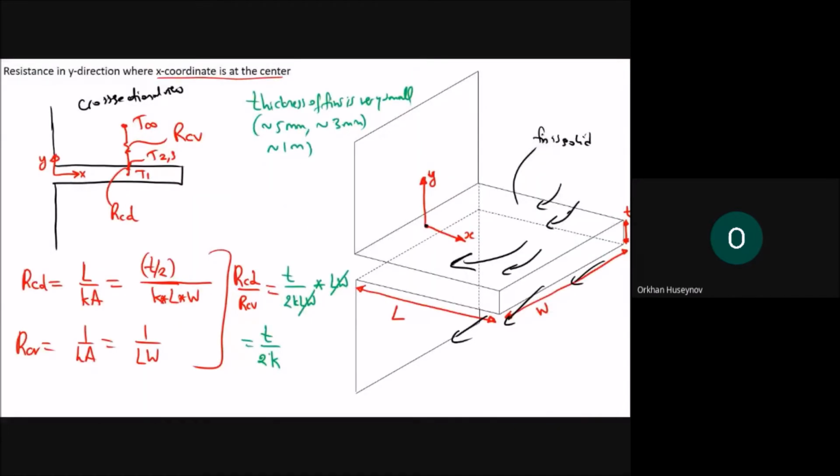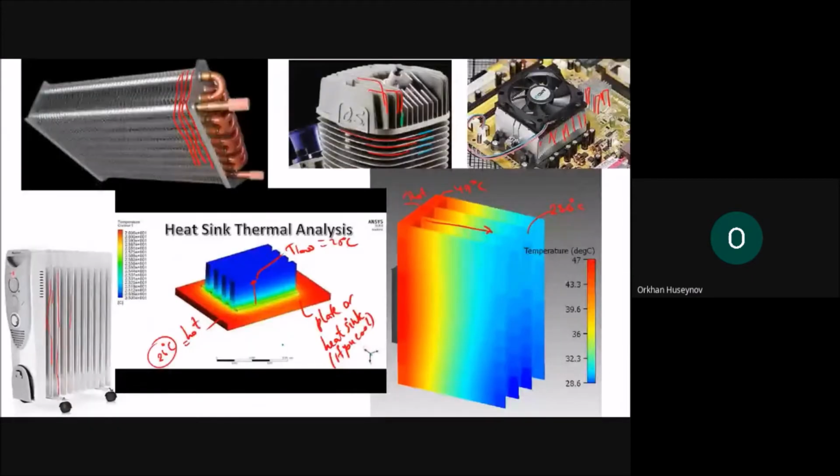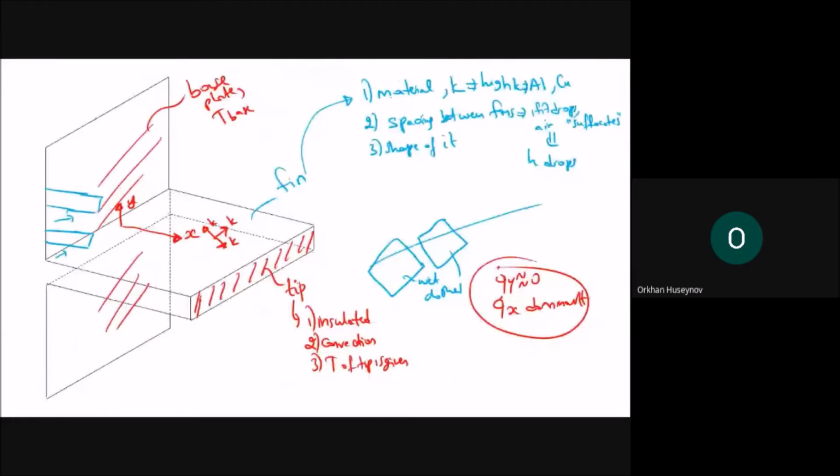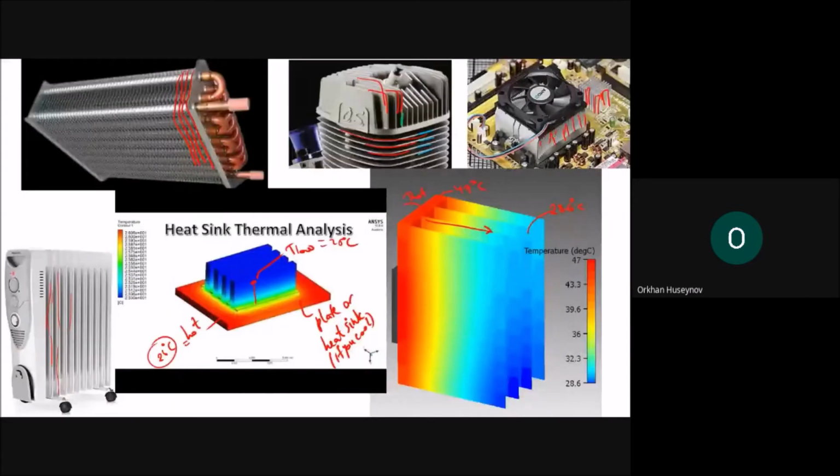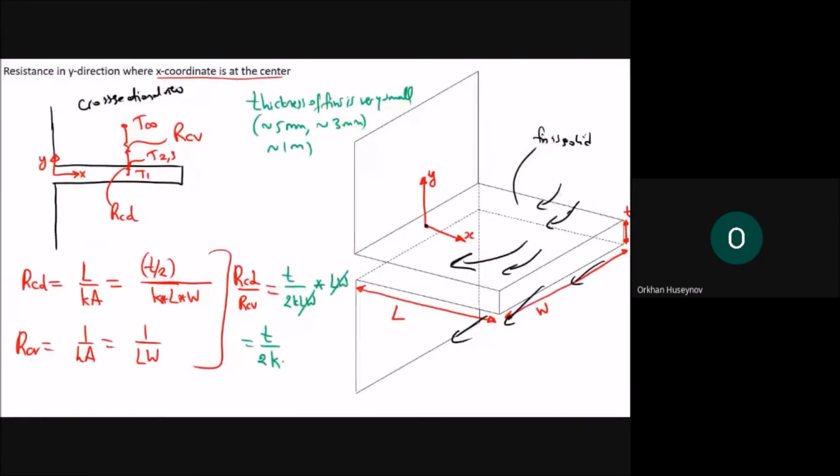And the K value here, conductivity, as I said in the previous slide, we want a material that conducts heat very well, because otherwise you cannot cool this one. Therefore we use aluminum or copper, because otherwise the plate will not cool. Okay, and since the thickness is very small and the K is very high, it is very high for effective cooling.